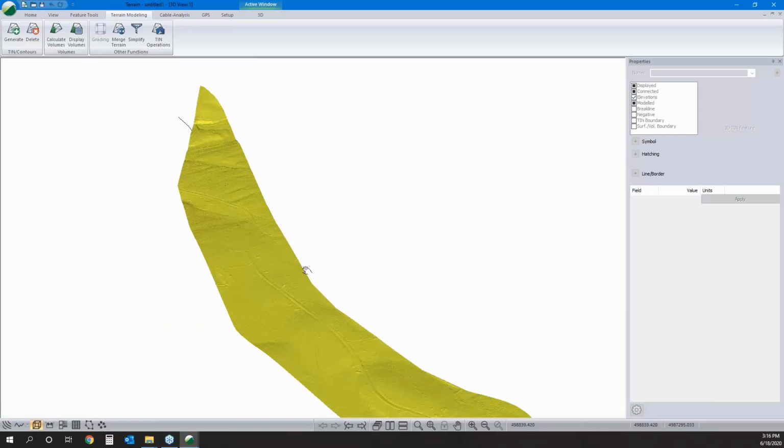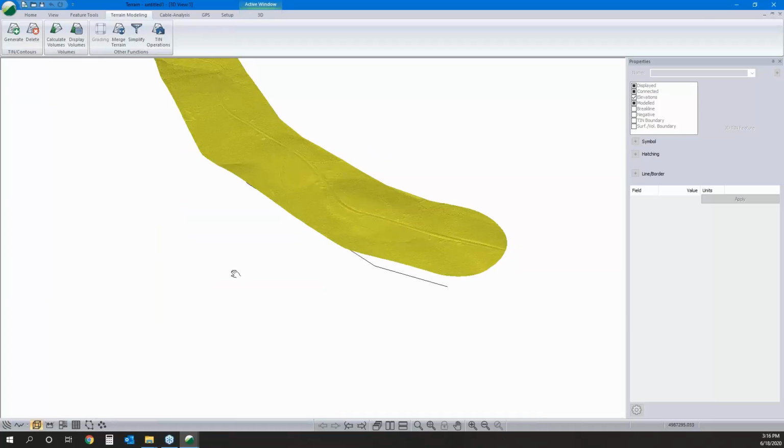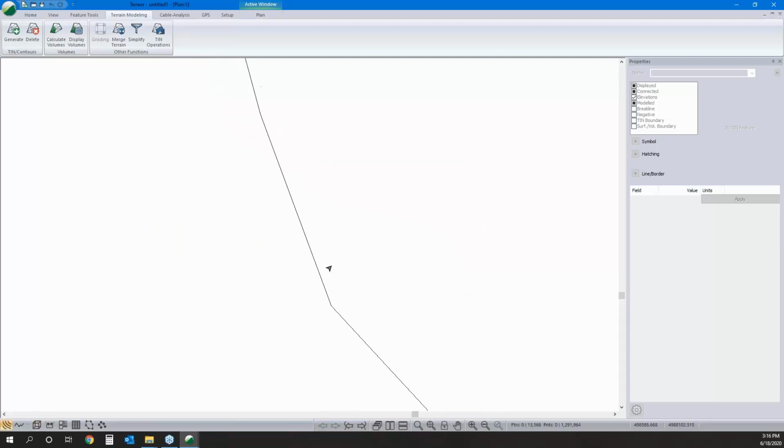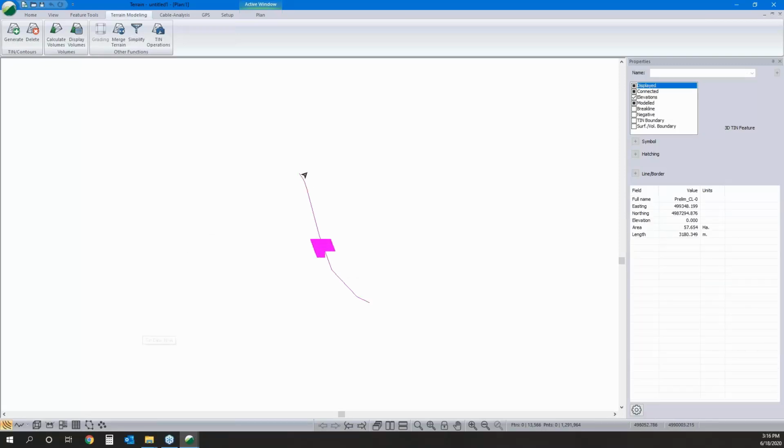And we'll click the 3D view, and there we can see our road. Now, I want to take, actually, we'll take Control A. The reason I have total station data for this one is we don't have the coverage we want with our LiDAR data. So just as those draw, we can see there's a pretty abrupt edge here, and that's just because my LiDAR tile doesn't cover that. So putting those two data sets together, I'm going to use the merge tool.